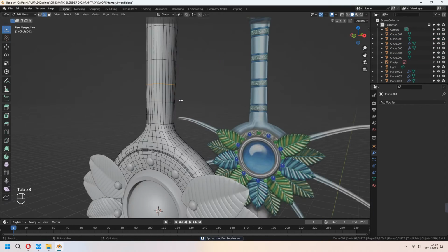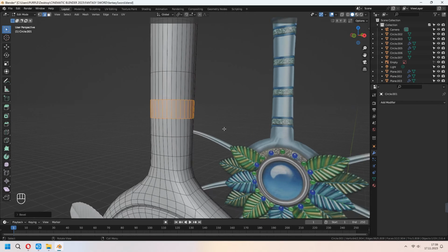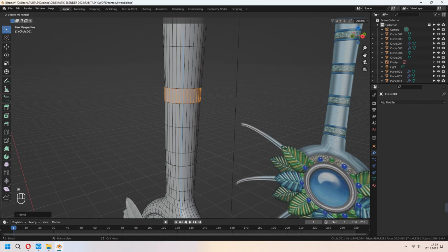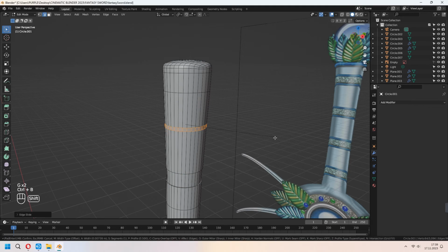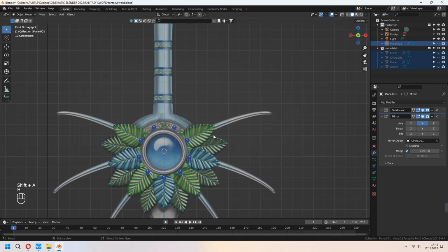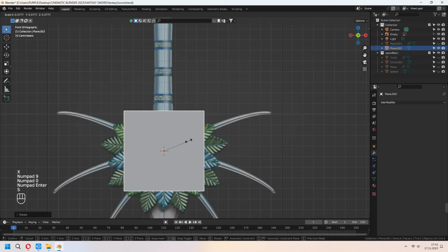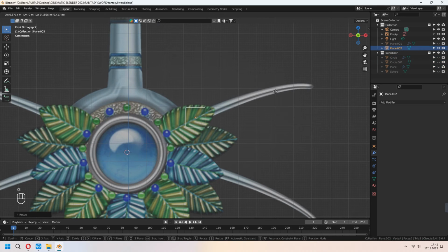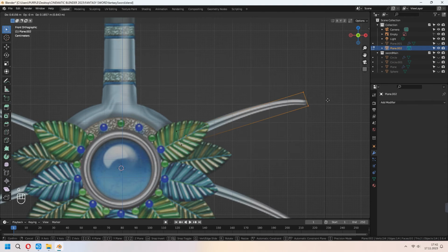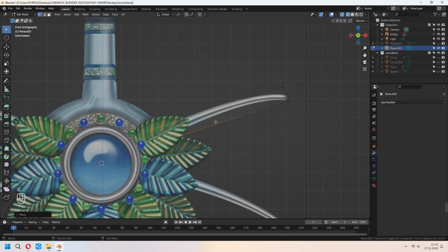Now for the holder spot, if you want, you can add some extra spices. You can Ctrl B to bevel, E to extrude, right click and Alt S to scale for this. How you want, that is your model. You don't have to make everything like your reference image. You can add different features in here. For the side back parts, we are adding a plane, and again the same and simple method, Ctrl R to add loop cuts.